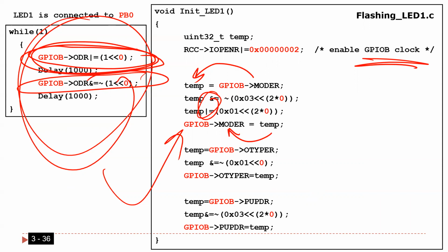You get what I'm saying? For some reason, the hardware is not allowing me to do that. I know from a software point of view, they are the same. There is no difference. However, the processor didn't allow me to do AND this way. It looks like you can only read or write. So here I read, then it changes, and then I write it back. This happened for me in these registers, but this one was okay. So it's just a question of what the processor allows.